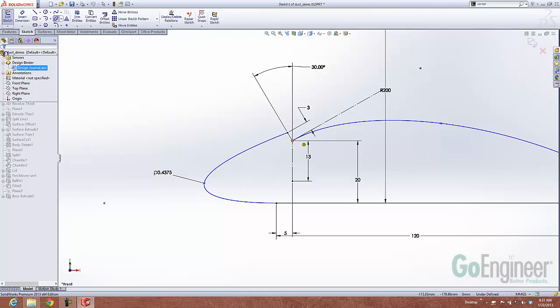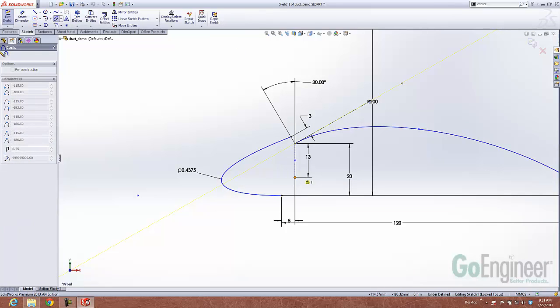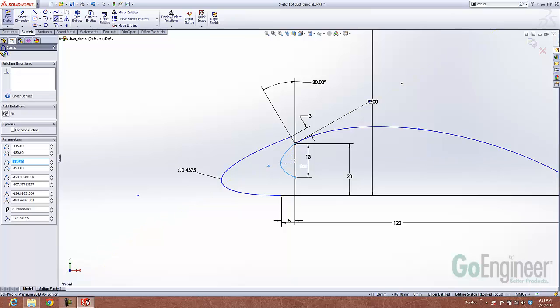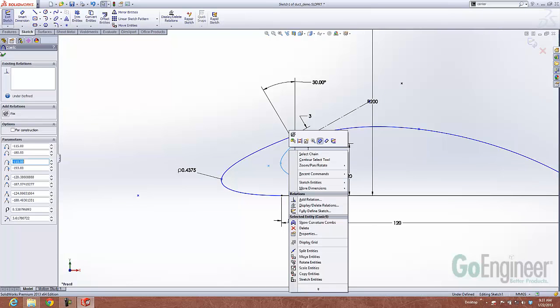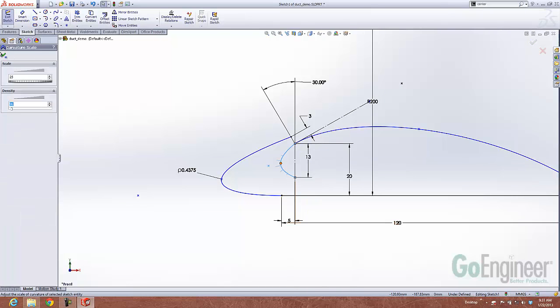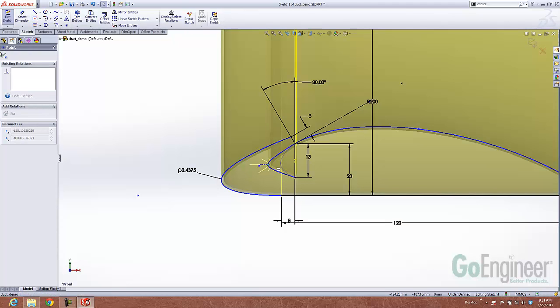And how we create the conics is click on an endpoint. In this particular case, we'll select another endpoint. You don't have to have an endpoint, but for this sketch it makes sense. And then define an angle and then a size right here. So you can actually come back in and place that. Now this guy here, if you want to, you can turn on your curvature comb so you can see how the curvature is affecting it. I do have a feature actually already built, so that's what it's showing me right here, that yellow. So I can place that in here.